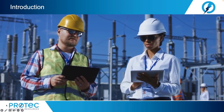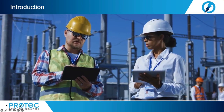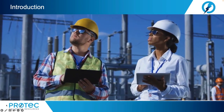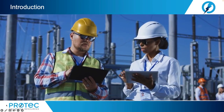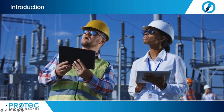Now, after a power or distribution transformer is disconnected from the power grid, or when a DC current is applied to it, for example, during a routine winding resistance measurement, the transformer core is likely to have some remnant magnetism. This remnant magnetism will generate high overcurrents when the transformer is re-energized, and this is commonly known as transformer inrush current. This inrush current, which runs for a few cycles, reaches a maximum when the polarity of the half cycle is the same as the polarity of the remnant magnetism and could damage the transformer itself or other components connected to it. Now, to avoid this undesirable effect, a transformer should be demagnetized after testing is complete and before being re-energized.